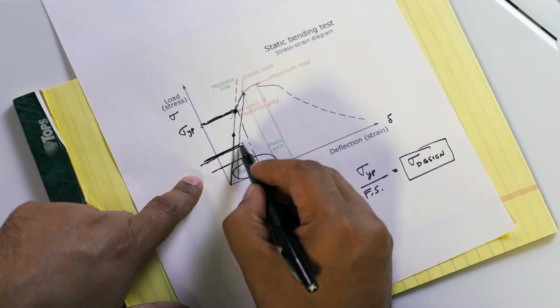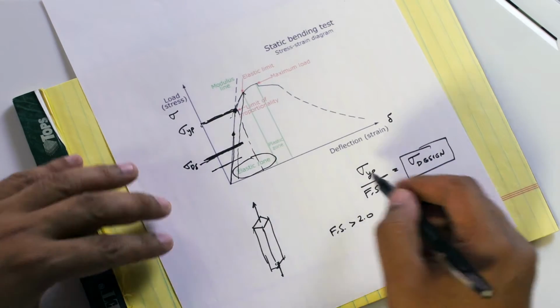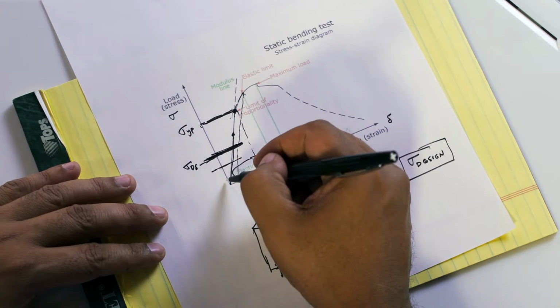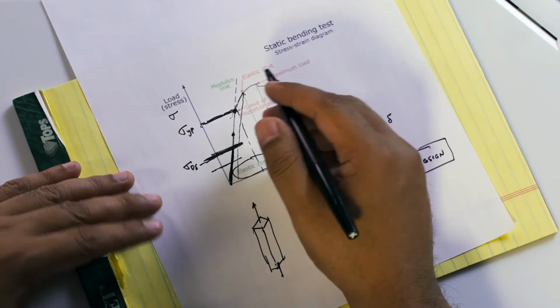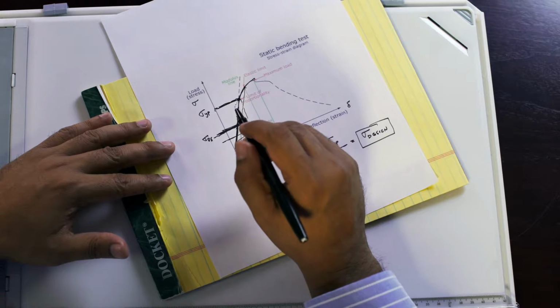So by limiting our design stress, let's say we're using a factor of safety of 2, that means we're only using about 50% of the yield point capacity. So the entire structure will always perform in this envelope. And then maybe in some dramatic situation it might go beyond that, in an earthquake, in a hurricane, or in a tornado, and in some very, very extreme circumstances, it may actually break. It may actually go all the way here, and it'll tear. So we try to prevent that from happening, and so that's why we have factor of safety.